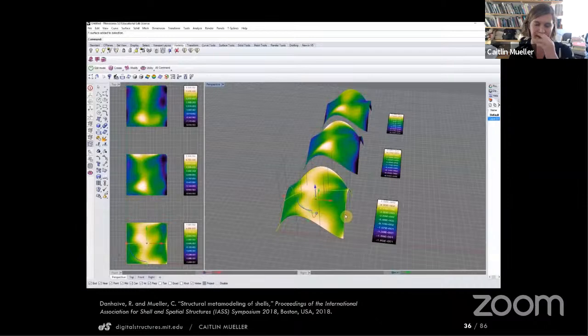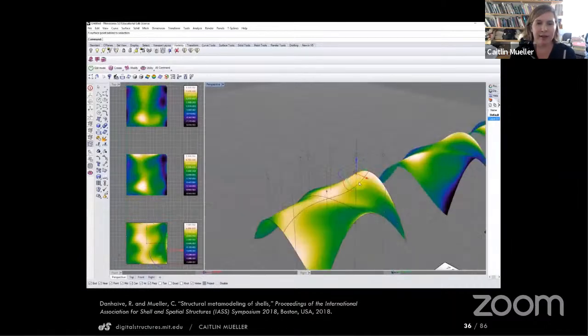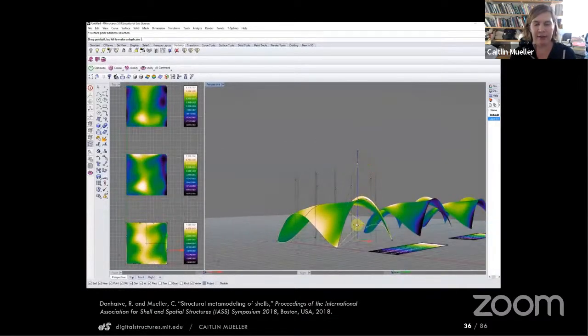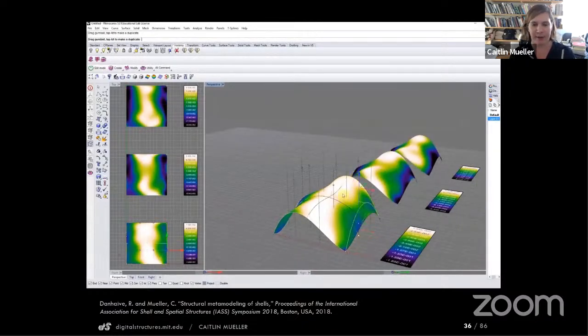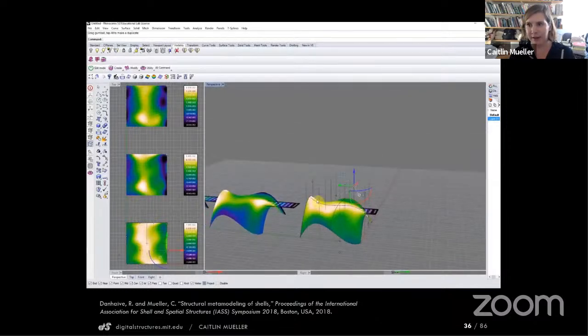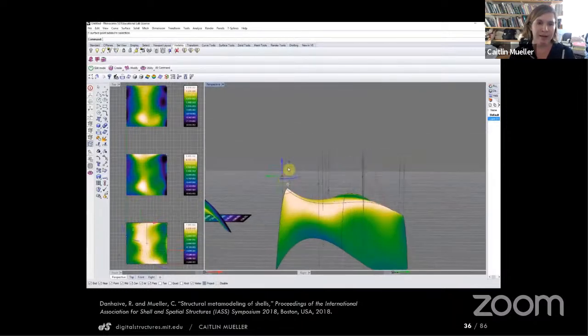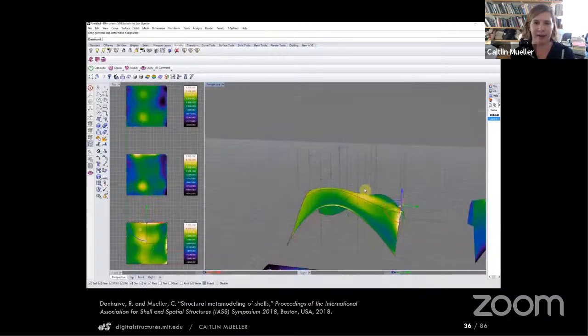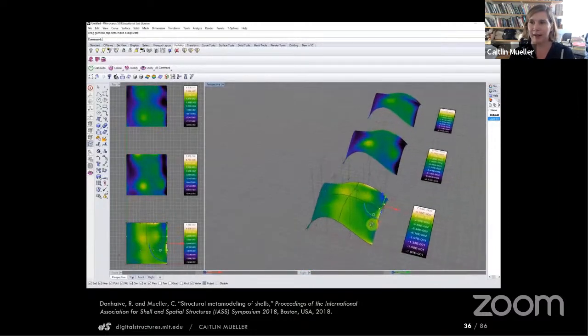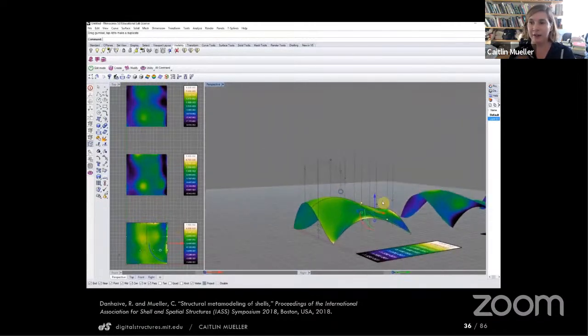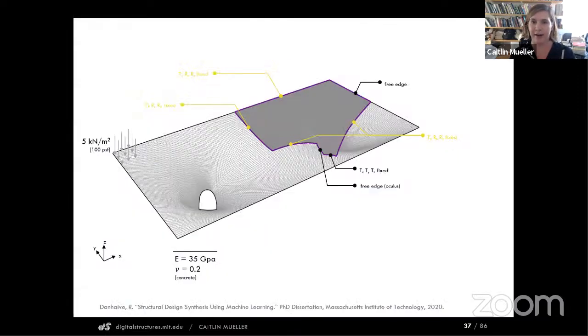And so, for example, what this means is that we can sculpt the design for a shell and get a full response instantaneously through the surrogate model. Here it's predicting X, Y, and Z displacement of the shell under loading. And we're not bothered by sending this to another program or running code. It's just happening live within this really interactive sculpting environment, within a CAD environment. And this starts to move things that used to be verifications into really design inputs. We can start to use this information to guide our design.